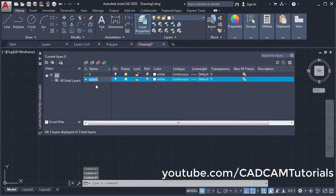Then you will have to give a proper name to the layer. You can use the logic of line types, like you can give the layer name as outline, center line, hidden line, or you can give a name as per the thickness you are going to use, like thickness 0.5, thickness 0.3, like that. If you are creating some civil plan, you can give names like wall, window, doors, and like that. So the name you specify here should be a meaningful one. Suppose I will name it as continuous.